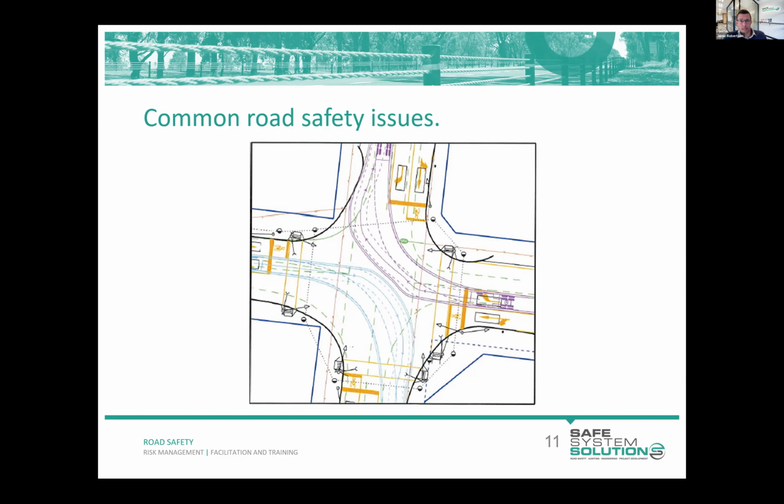As an auditor, we would then need to think about what is the consequence of the intersection being designed in this way. It's unlikely that two vehicles approaching from opposing directions would continue into a collision situation. They would probably take evasive action. It's possible this could result in one of those vehicles ending up in an area they shouldn't. But stepping back, I suppose we need to think about what is the choice of design vehicle from each approach, and what is the likelihood of two of those vehicles arriving at the same time.